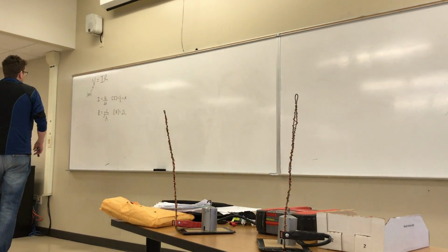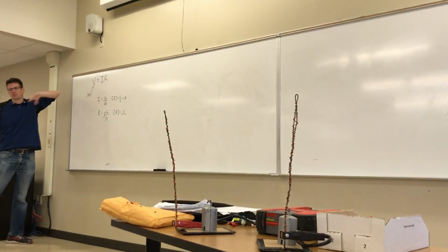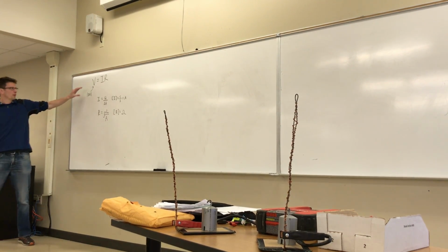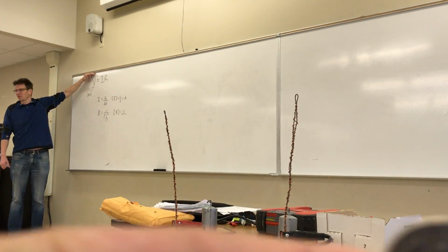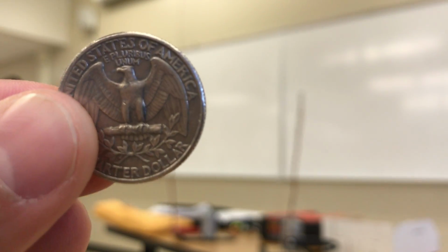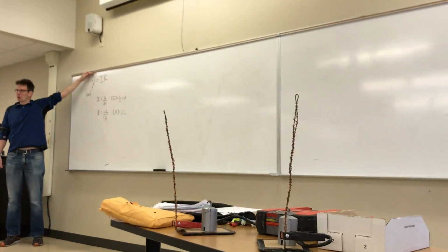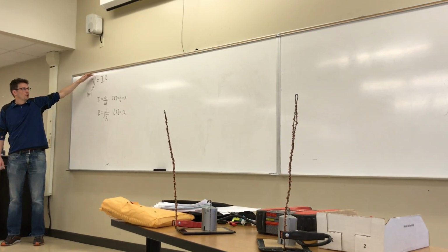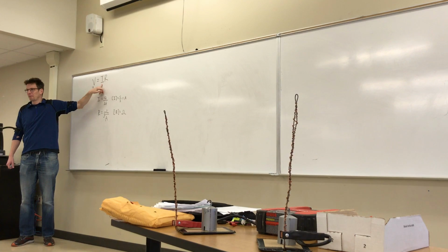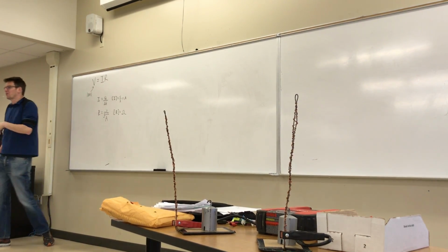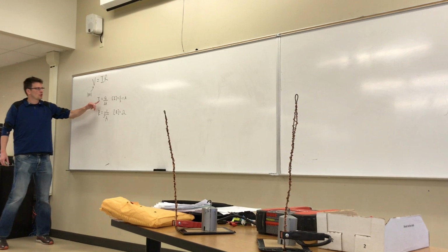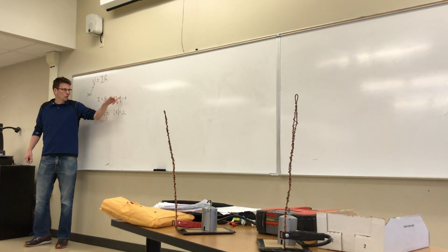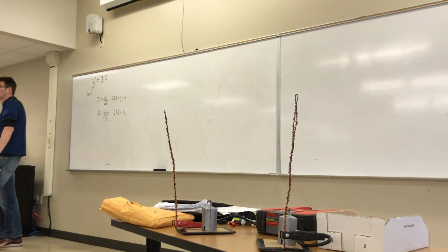Okay, so Ohm's law right here. We talked about this last time. In circuits, when we say V, we really mean the voltage difference between 2 different locations. And if you apply a voltage difference across 2 different locations, that provides motivation for charges to go because they can lower their potential energy. And so we will get the amount of current, and the amount of current depends also on how much inherent resistance is in the way of the flow. So current, that's the charge that flows per time. The units are coulombs per second, that's amps.